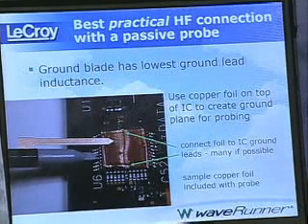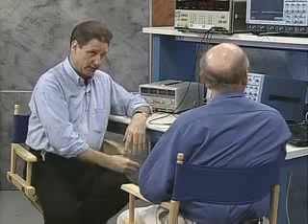That's a clever thing. So you build a little ground plane on top of the chip, and this is great for us because a lot of the boards we work on are just so heavily populated now, 12-layer boards. There's no place that you can have pads handy, even if you can control the layout of the board, you can't put that pad in to be able to check. Well, sometimes you're lucky and you've got test points and you can probe them with normal probing accessories. But sometimes you're not so lucky and you need something that's a little more innovative.